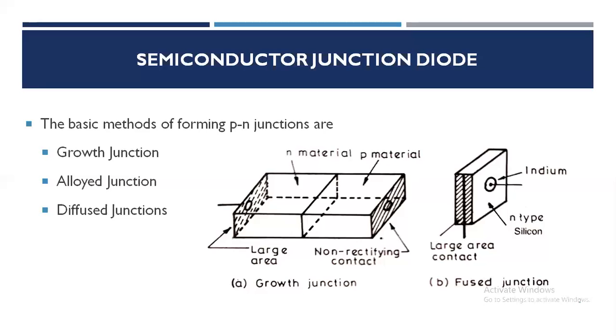An important exception, however, is the epitaxial growth of p-n junctions, which is used widely in integrated circuits and for other applications. An epitaxial layer of one type can be grown on a substrate of the opposite type to form a sharp, single crystal junction.